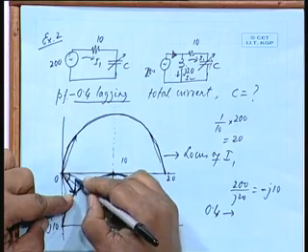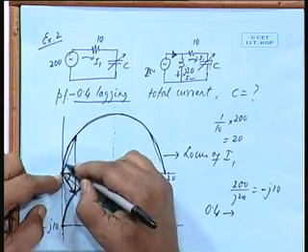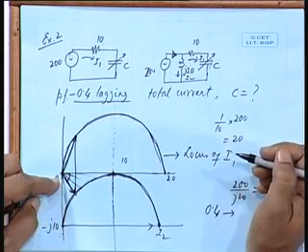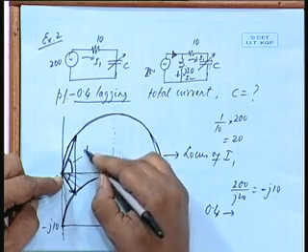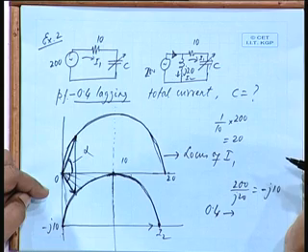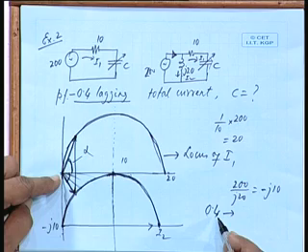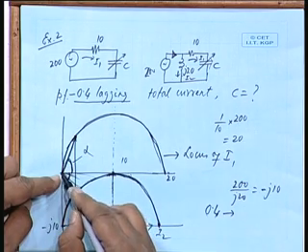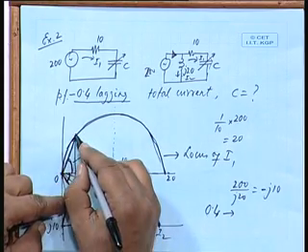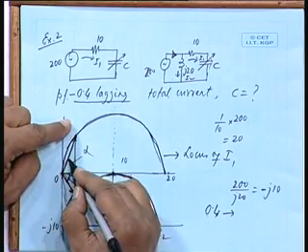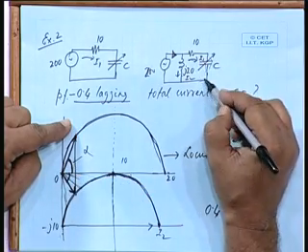Shift it vertically, wherever it hits, this is the current I1, is it all right? Measure this angle, suppose that angle is alpha. How to get alpha? First of all, you have the given power factor, the corresponding angle you draw here and then find the current. From there you draw a vertical line, you reach here. So, that gives you the angle alpha of this current, all right.